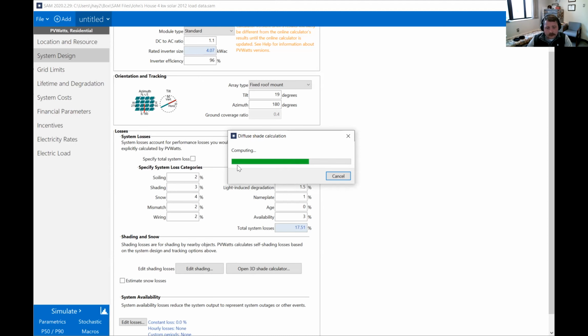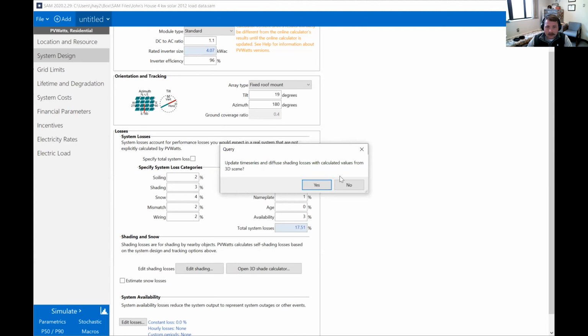The most powerful tool for estimating shading though, honestly, is to go visit the site and stand where the solar is going to be and just visualize the sun moving across the sky. There is not much that can replace going and visiting the site. And honestly, there are solar installers that love to give you a quote without having ever visited the site. That's a problem.